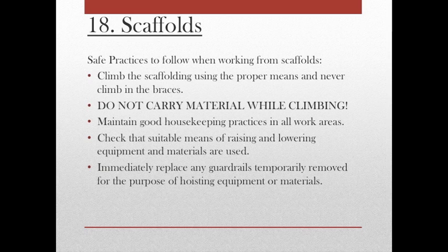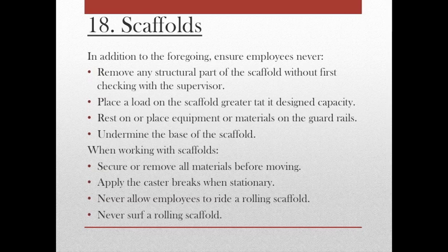Maintain good housekeeping practices in all work areas. Check that suitable means of raising and lowering equipment and materials are used. Immediately replace any guardrails temporarily removed for the purpose of hoisting equipment or material. In addition to the foregoing, ensure employees never remove any structural part of the scaffold without first checking with the